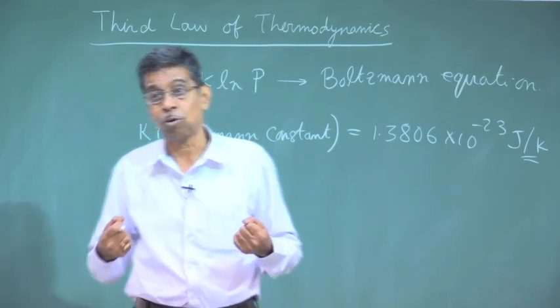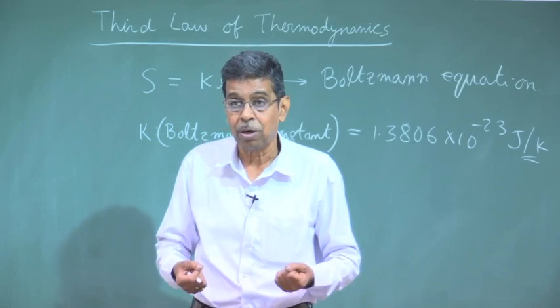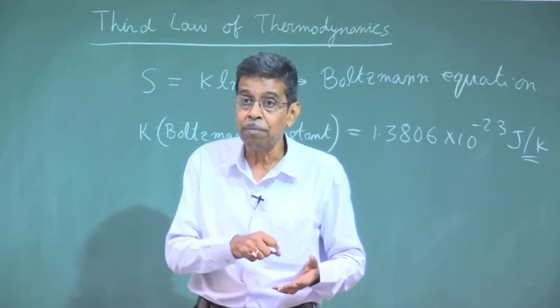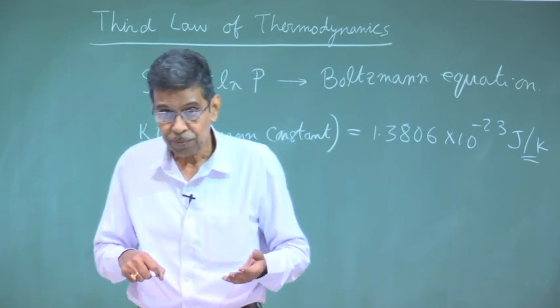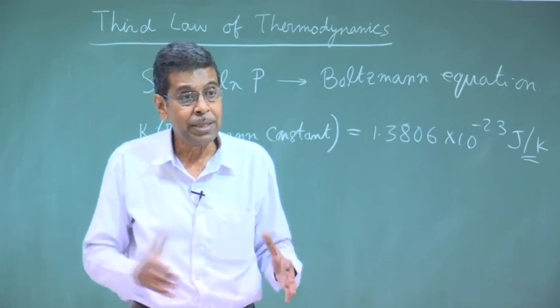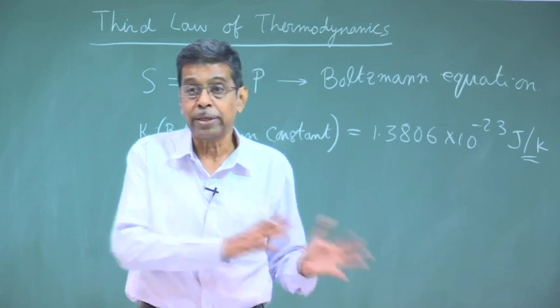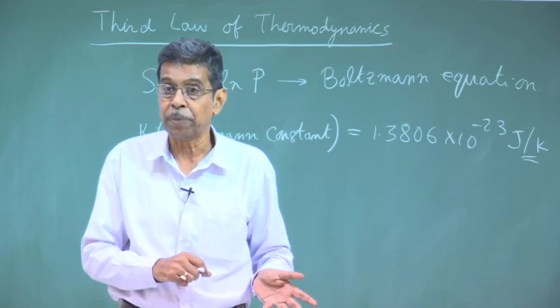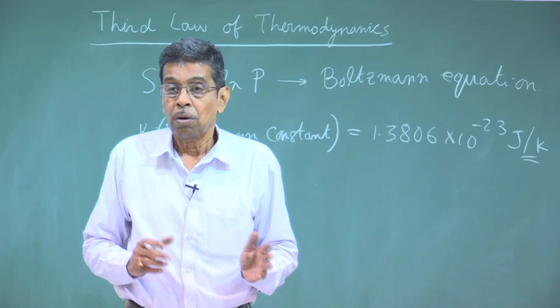Most gases are cooled by utilizing this effect, where the initial temperature is usually lower than the inversion temperature to realize this cooling effect. Otherwise, the gas has to be pre-cooled to a temperature below the inversion point temperature of that gas.